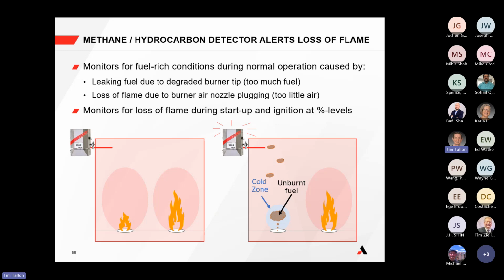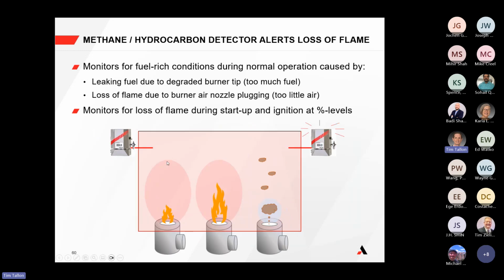high fuel in the firebox before the next light off. And so, in the case of a fired heater with multiple burners, multiple detectors would provide that ability to look across zones as well. So it's also important to think about, well, how big is your firebox so that you can monitor for the different various zones that you have in front of you.